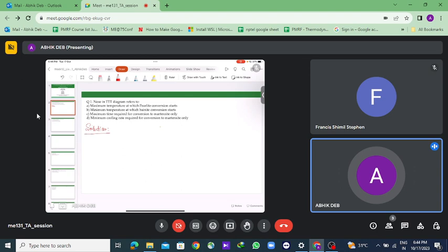This is the martensite, this is the pearlite region, this is the bainite region. If this is how the cooling happens, then it will form pearlite. If this is how it happens, then it will probably form bainite and then martensite. But for only martensite, this is the nose. So any cooling rate faster than this will result in the formation of only martensite. Okay.